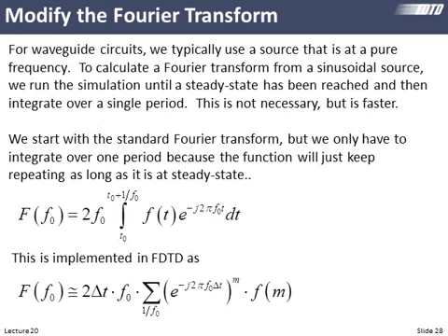That previous movie you saw, that reached a steady state probably somewhere around halfway through the simulation. We see that initial pulse come in, kind of come around the bend, but at some point it's really looking the same, and it just repeats every wave cycle and looks the same. So what we can do is wait until we reach a steady state and just do our Fourier transform over one cycle of the wave. And so we can get simulations done a bit faster that way. It's a little bit faster for calculating steady state fields.